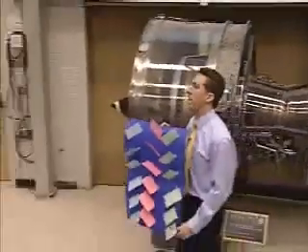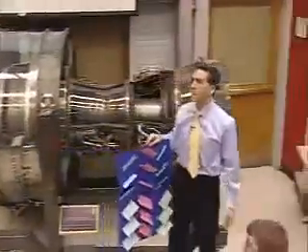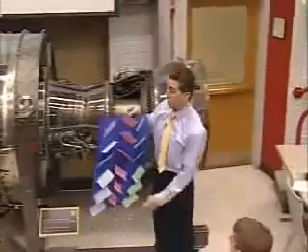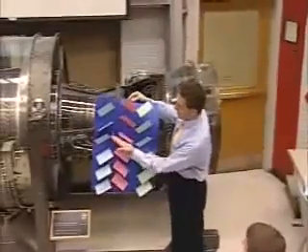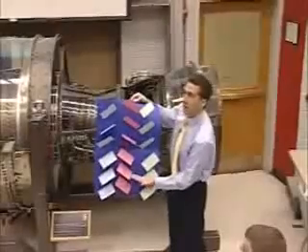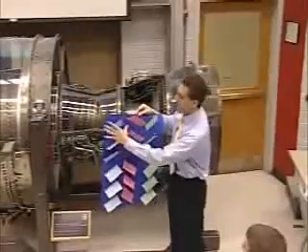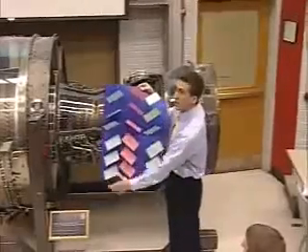Yes? In that problem, aren't we saying that the streamlines are coming in at an angle, because you even have velocity vectors coming at the angle, but wouldn't it just be coming straight through? It could be, but it turns out that if you have a lot of vanes, the flow tends to follow the vanes. Right? So that problem is a stator. So it's just a fixed set of vanes.